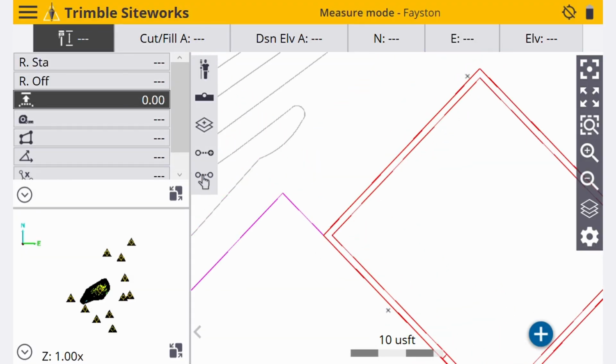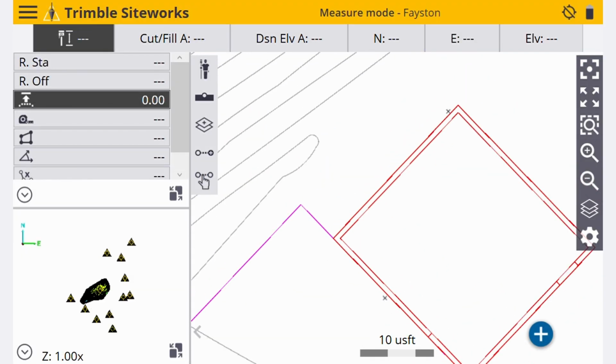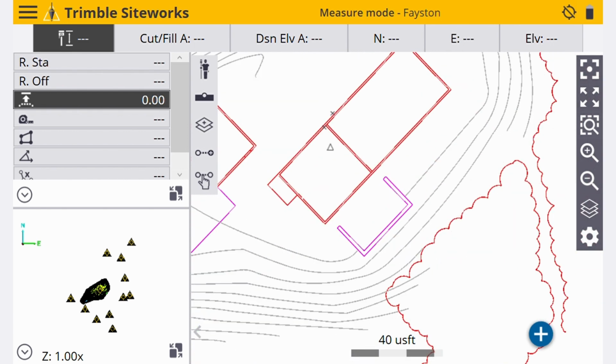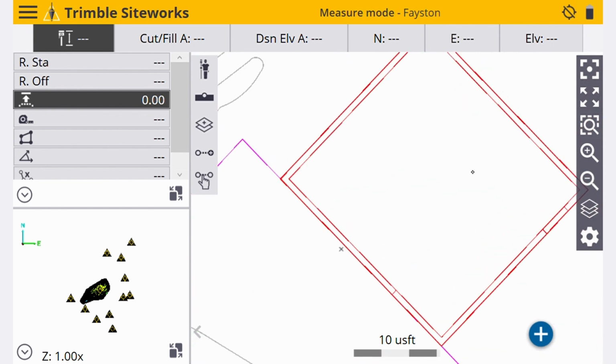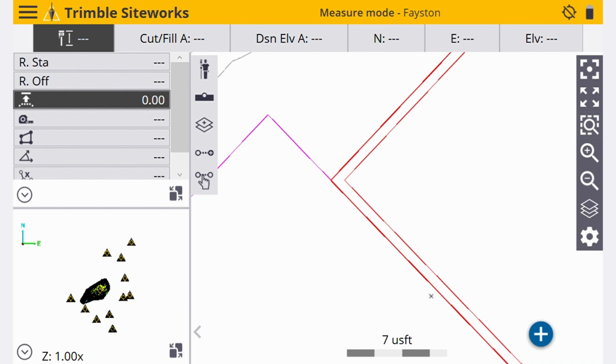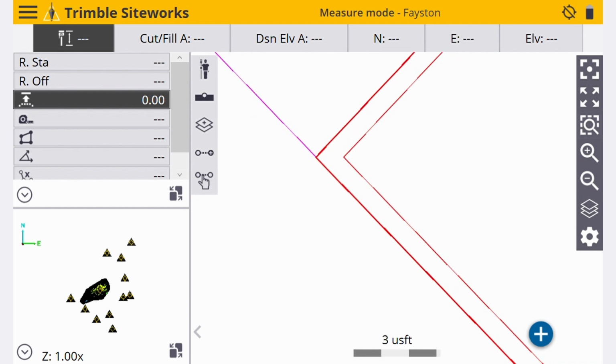So step one is going to be we're going to get this building slab in for visual reference, because at the end of this, what I want to be able to do is just have a new design that we're going to work on. We're not worried about this whole section of the site over here. That's all in. We're only worried about this backyard area. So first thing we're going to do, we're going to get this slab in. We're going to get the finish grade, top of topsoil, in here.